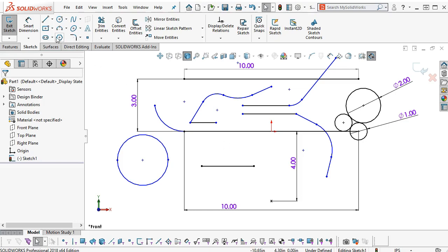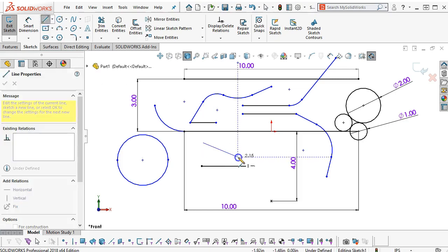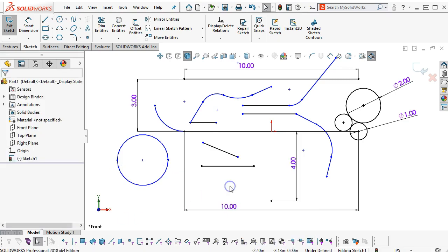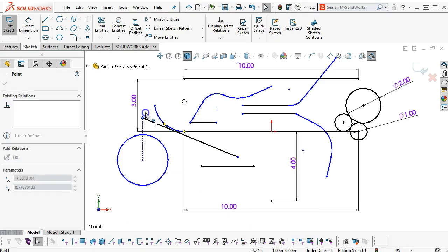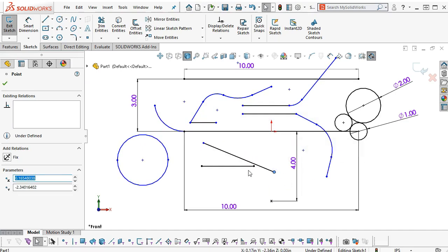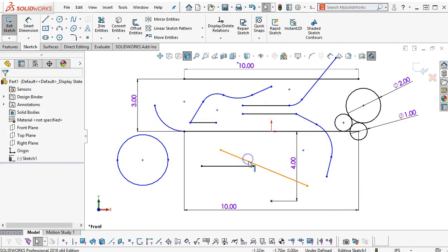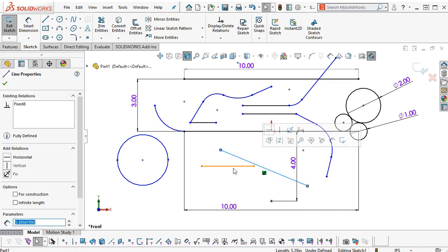All right. The other downside to a fixed line, let's just put one here, and I click on fixed. Notice that I had the object. My two endpoints are still movable. Where previously I picked the endpoints to be fixed, and the line would stay in black because that is the definition of the line between the 2 points. In this case, the line is still capable of moving, or the endpoints are still capable of moving even though the line is in location.